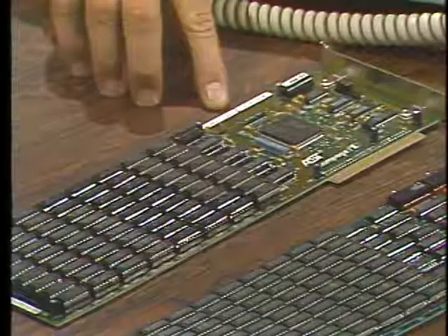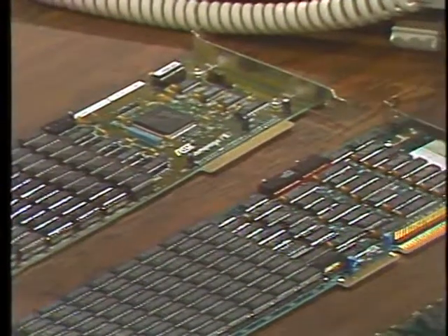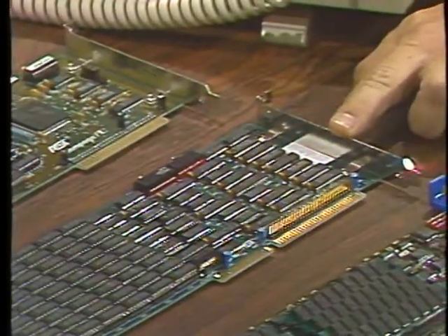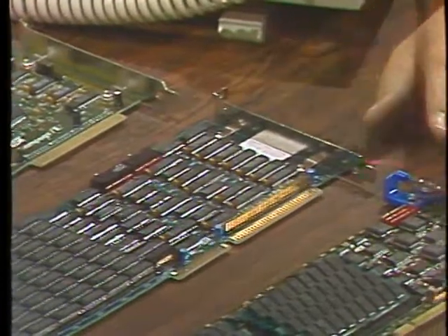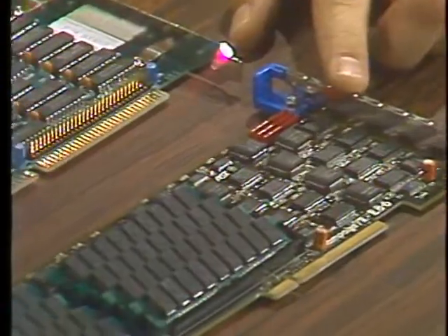Okay, tell us about this board now. Sure. What we're going to be showing with the Premium 286 is an expanded memory computer, but we wanted to emphasize that it's not simply a function of the computer itself we're using. We also have boards that span the entire range of processors and bus types. For example, for an 8088 machine, a PC, XT, or even the Model 30, the 8086, there's the Rampage 2, which is a 2 megabyte EMS 4.0 memory board. For 286-based machines and compatibles, we have the Rampage 286, and for the Model 50 and 60, for the PS2 line, we have the Rampage 2 286. All three of them provide 2 megabytes of memory.